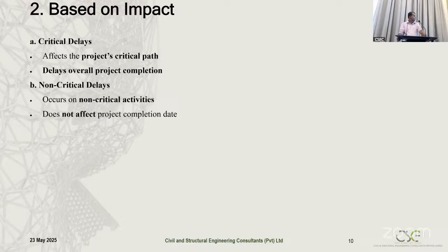Based on the impact, the delays we can categorize that is impact critically to the project completion. Critical delays and non-critical delays. Critical delays affect the project critical path and overall project completion. Non-critical delays occur for the non-critical activities and do not affect project completion dates.